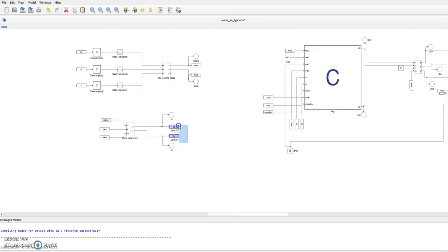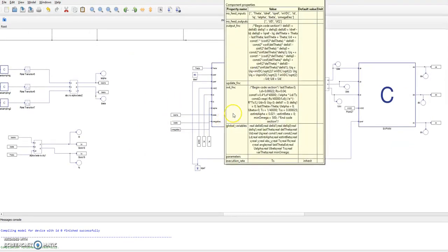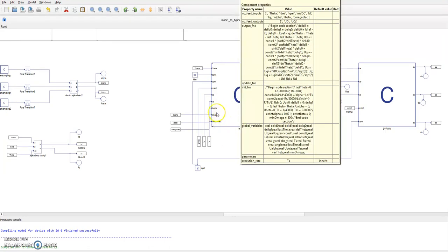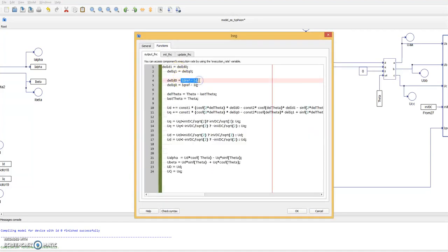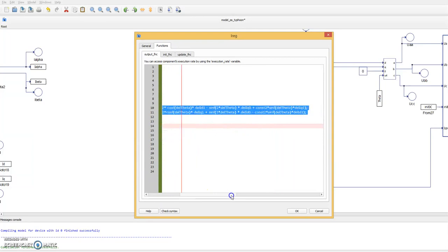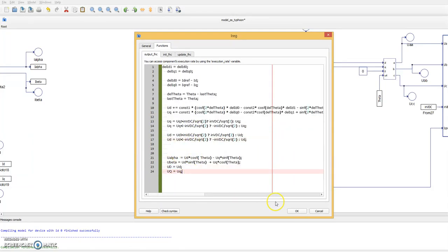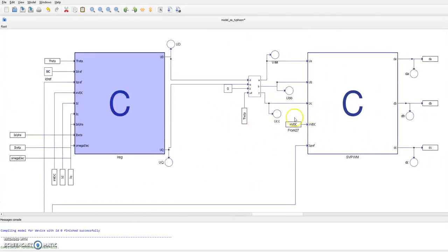Now we have measured the currents in the direct quadrature system, and those currents are in the current regulator block. The current regulator takes on all these variables as inputs: the position of the system, the references from SCADA input, measured currents in the direct quadrature system, and takes the signal of error, and after some regulation, which is given right here, gives the voltages in the DQ system to be later on used by the space vector modulation block.